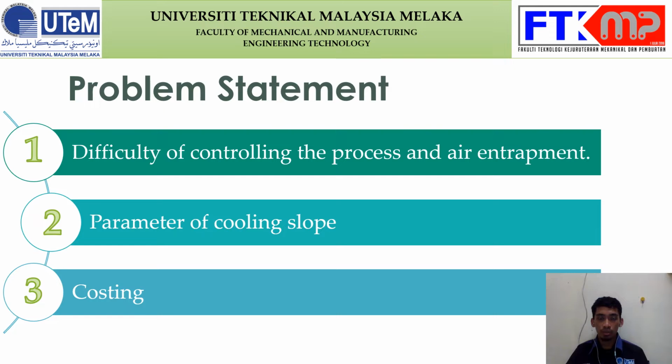The problem with this method is that it cannot be applied to all applications. This is because it is difficult to control the process, and there is air entrapment. Second, the parameter and angle are the important keys that affect the microstructure directly. To run this experiment, a water cooler is needed, so it adds cost for maintenance.